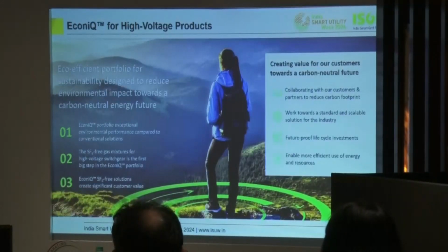Our idea with retrofill is to provide value addition to our customers, because if I mention India, from Hitachi Energy itself for the 400 kV, we have more than 250 bays which are already installed. And even in one bay of a typical 100-meter bus duct, I would say, there is a proportion of SF6 equivalent to 750 kg. So we are talking about a potential removal of SF6 gas, 750 kg into 250 GIS bays, or maybe a little less. So this is a high proportion, and this solution can actually contribute to the government's initiatives and customer initiatives on the reduction of carbon emissions.